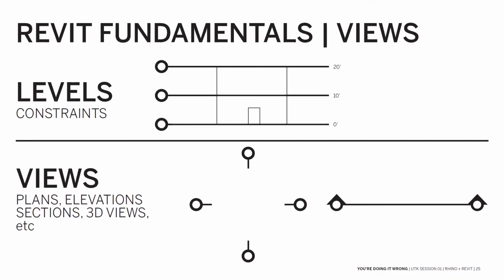So how does Revit work? So Revit ties everything that you see in it to levels. So levels will then represent the constraints that you're using. So level 0 will then be the floor. So the base of the building will be attached to level 0. And then each wall can either go up to a level, number 2, which in this case is 10 feet above level 1, or the second floor will go from level 1 to level 2. And so things are constrained towards levels.